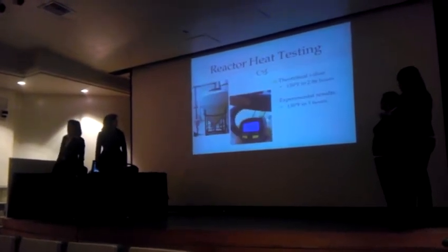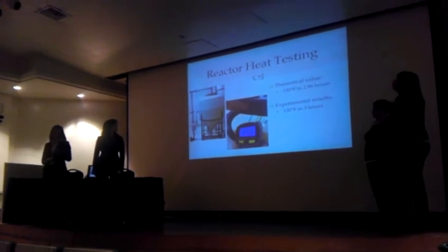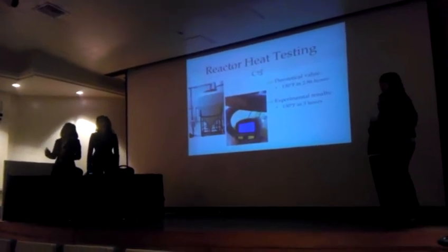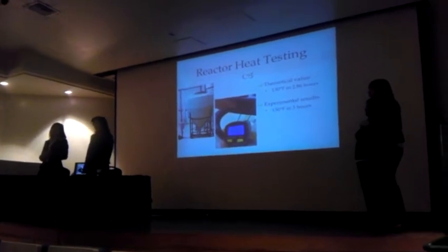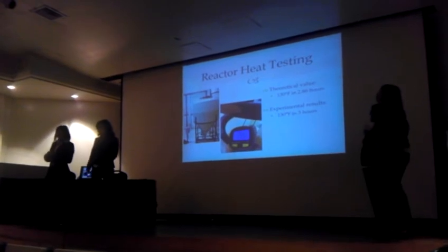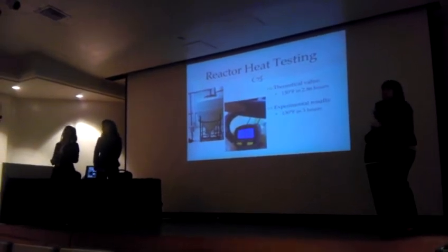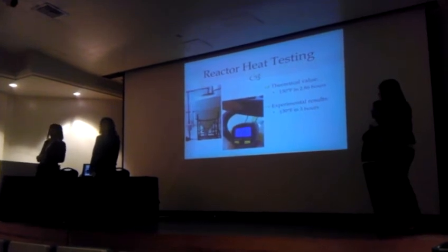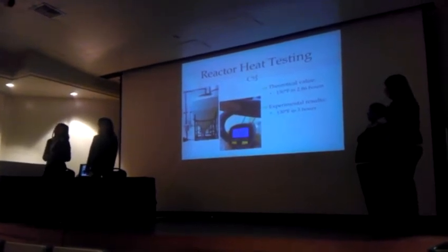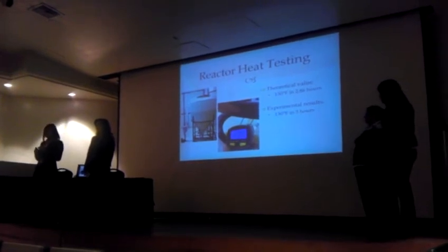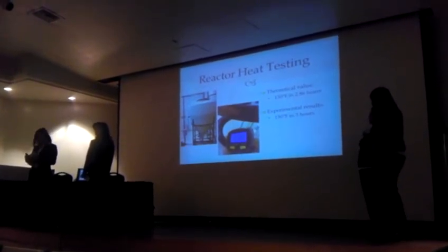All right, and for the reaction process, we had to calibrate the heater to make sure we set it at a proper setting to ensure that it maintained a temperature of 130 degrees Fahrenheit throughout the entire reaction. So basically, we just ran some water through it and did some trial and error to try to get the knob right, and then waited until the water reached a steady state of 130 degrees. We finally found the proper setting and adjusted it accordingly.